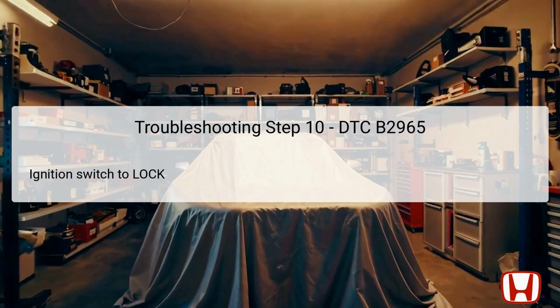With repairs made to the wiring, the technician should turn the ignition switch back to the lock position. This step is essential for safety and to prepare for testing continuity in the next step. By ensuring the ignition is in the off position, it prevents any accidental shorts or system failures while measuring continuity. This action also allows for a clean slate when reconnecting any components for the next phase of testing. Following this procedural approach greatly reduces the risk of new errors entering the system due to ongoing diagnostics.